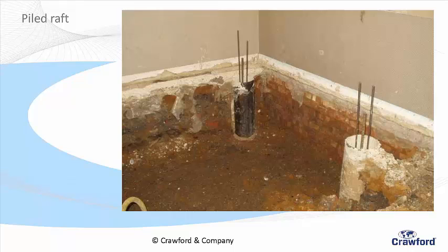When that tree does come out, we could potentially get some recovery off the ground. If that ground recovers, it could lift my piles up. So I need that ground to slip by a sleeve. The pile has got a loading at much deeper depth. So when the ground swells, it just slides past. Yeah? So we end up, unusually with the pile draft situation, where we dig down into the ground a bit further and leave a nice void, so that when it recovers, you've got a nice gap to play with there. Does that make sense? So it's called an anti-heave precaution.